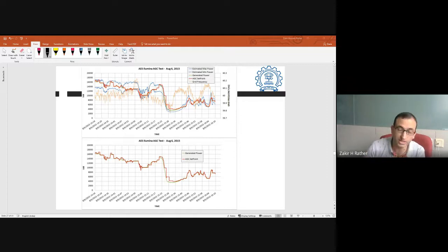Now the question that can arise is, as you pointed out: do we need to operate it throughout its operation at a non-MPP point, or only in anticipation of participating in inertia around that particular time? As of now, some of the grid code regulations, for example in Canada, Hydro-Quebec, and some other parts, mandate the control capability only. It means the solar PV or wind turbine generator should be capable of providing the inertial support, but they do not force them to operate at non-MPP, because there is a revenue loss involved in that.